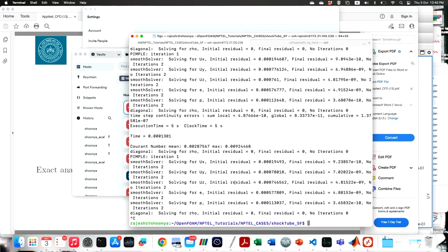So, it depends on what kind of solver you use, whether it is pressure based or density based. In the pressure based solver also you can have the energy equation, right. So, that way it can solve either for pressure or some other quantity, right. You need 5 equations, right. So, here it is solving 3 momentum and enthalpy, and finally it is solving for pressure, okay.